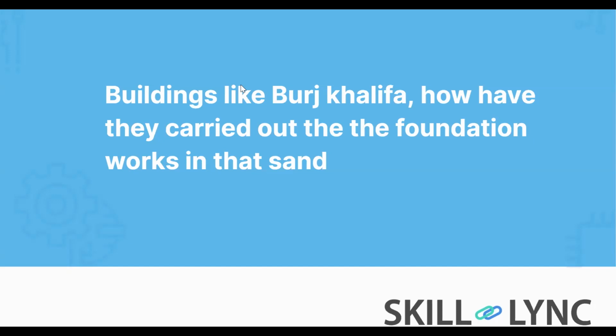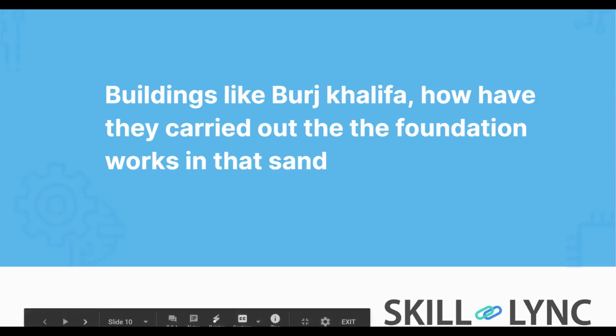So what they do for Burj Khalifa or any building in the Middle East, mostly they will go for basements, obviously, because it's required, and then they go for piling. And these piles were maybe anywhere between 30 to 60 meters or even longer in some cases, and they will reach the rock strata below. So that is how they provide the foundation. It will not be a raft foundation, it will be a raft on pile foundation, and these piles will go all the way down to the rock strata. I think that answers the question.